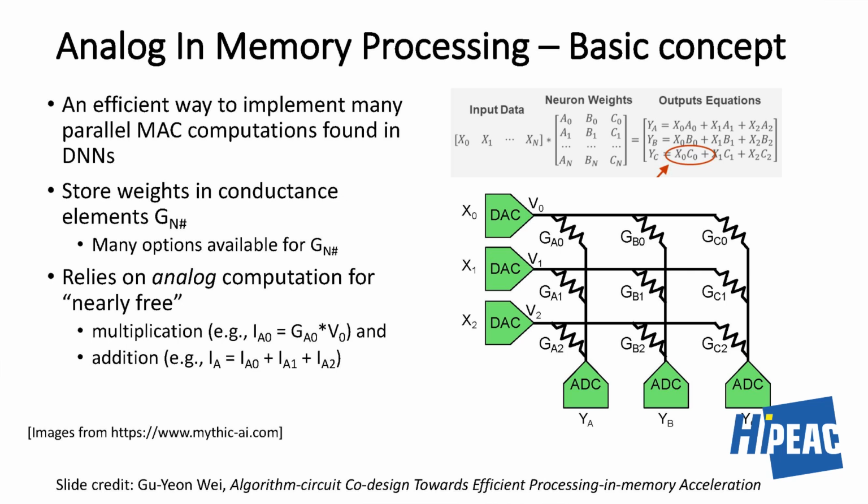What you do is you first divide the inputs into bits. Then for each bit you send a current in. The bit cell does a voltage difference here, and when you sum up the current, you get a dot product with the stored bit cells. That's the analog computing I'm talking about.